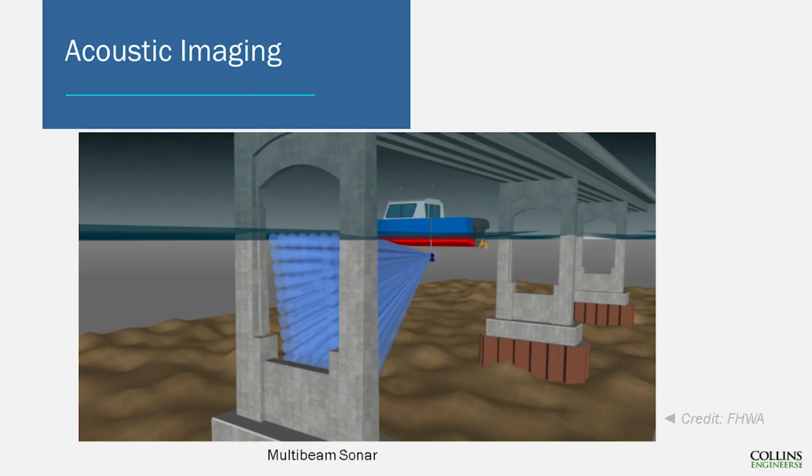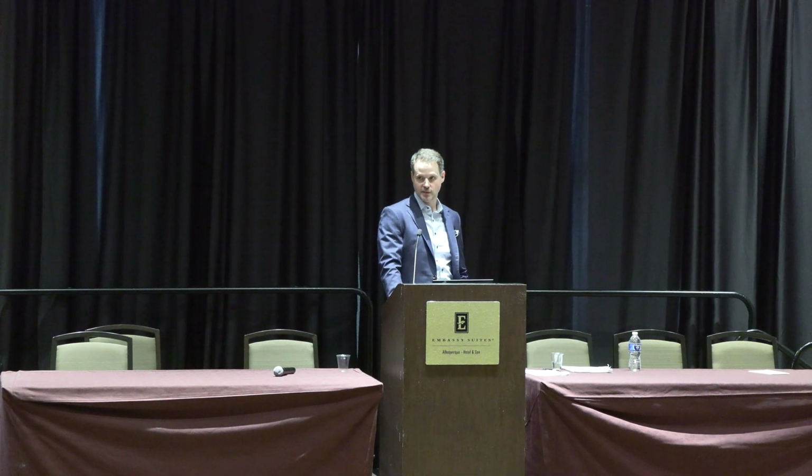So next up is multi-beam sonar, which some of you might be familiar with. Rather than a single beam, multi-beam contains many rows and columns of narrow beams that are insonifying a volume. This matrix of narrow beams allows for more dense data coverage, creating hundreds or thousands of data points with a single ping. Some benefits of using a system like this are that it creates a 3D image of the object you're trying to scan. It does have a high degree of accuracy and precision.